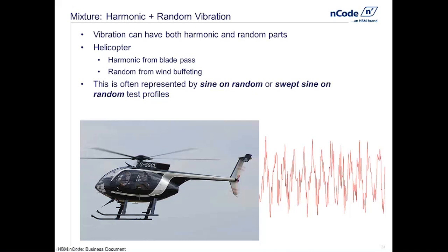Now the beauty of this is that all these different types of loading we can account for inside DesignLife. So if you can calculate stress and dynamics in FEA, and if the loading data can be collapsed down into the frequency domain representation like a sine dwell, random, sine-on-random, or swept sine-on-random, then DesignLife can take all that information in and do a reasonable job at a fatigue calculation while enjoying the benefits of working in the frequency domain.